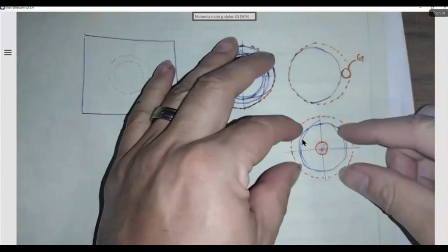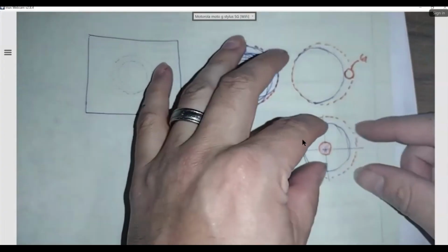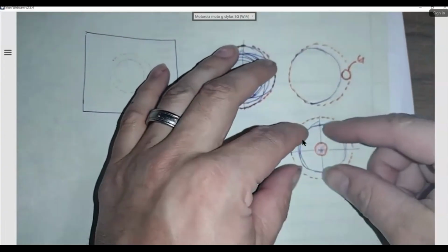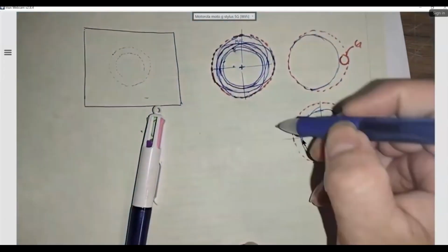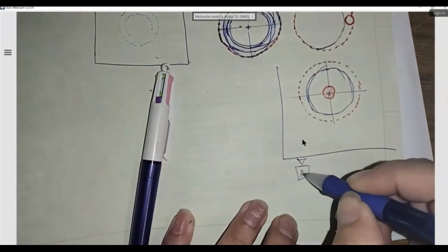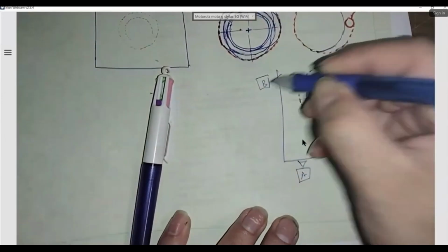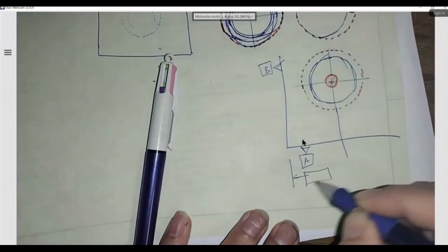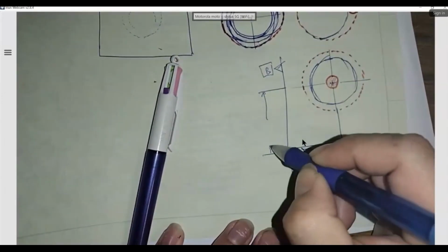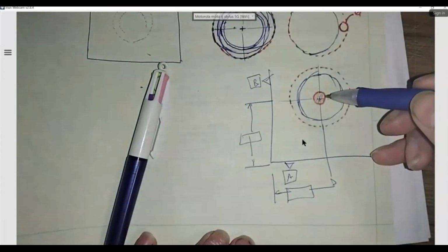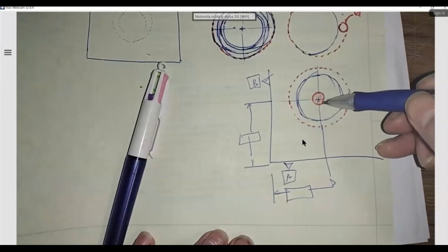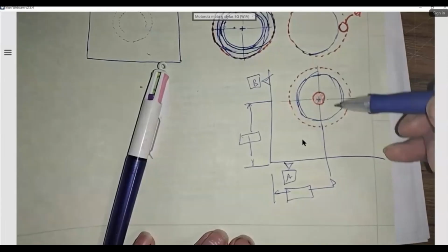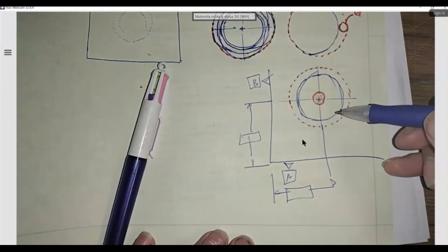I can grab my MMC, which is the biggest I can get, and I can shift it to the right, shift it to the left, shift it up, shift it down. And it doesn't matter where I put my pin, as long as I relate it to my datums. That's what I got to put it with basic dimensions. Let's call that the true position. True position is where the bullseye is, and it has a certain diameter that I call out in the feature control frame. My hole has the D, which controls the form.